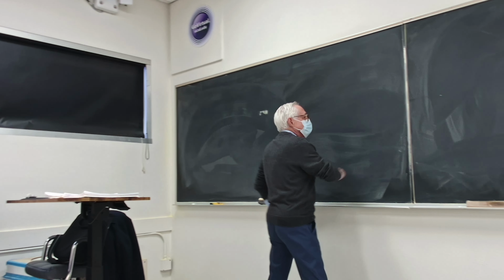Therefore, what do I have over there? m dot multiplied by h. So m dot 1 h1 plus m dot 2 h2 exits now, right? Minus m dot 3 h3 equal to 0. Agree? No Q, no W, no dE by dt, no delta Z, no delta V. V1 squared equals V2 squared. That's it. I have two equations.